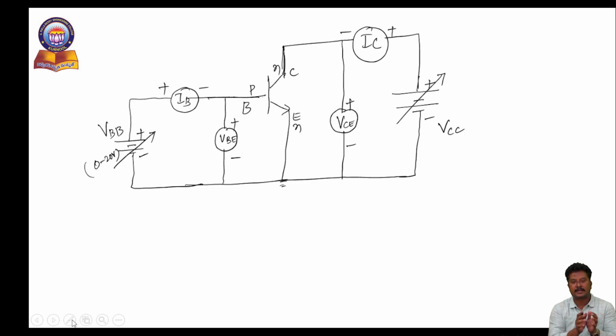Once you know the internal structure is equivalent to a two-port network, then we can define it with respect to electrical devices. Unless you convert the transistor into electrical components, dependent voltage source and dependent current source, it is not possible to know how this particular amplifier depends upon the internal structure. I have to design an amplifier for certain applications depending upon the conditions, so I have to know what the dependent and independent factors are. That is the reason why we are concentrating on this configuration.